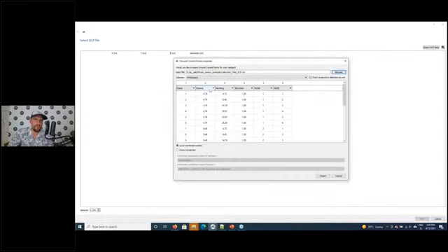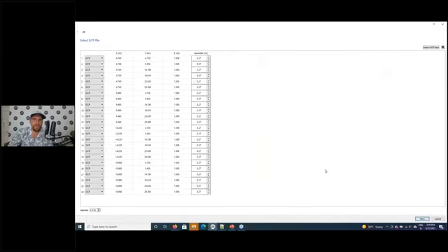By default, it will already read it in. It will read name, easting, northing, elevation, and these values that were used to calculate the positions will just be ignored by default. So this is all perfect already. Press next here.